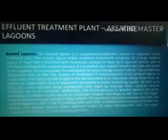And coming to the next topic, aerated lagoons. An aerated lagoon is a suspended growth process in a wastewater treatment unit. The aerated lagoon water treatment system consists of a large earthen lagoon or basin that is furnished with mechanical aerators to maintain an aerobic environment and to prevent settling of the suspended biomass. It is furnished with an inlet at one side and an outlet at the opposite side, enabling the wastewater to move through and be held for the specified detention time.